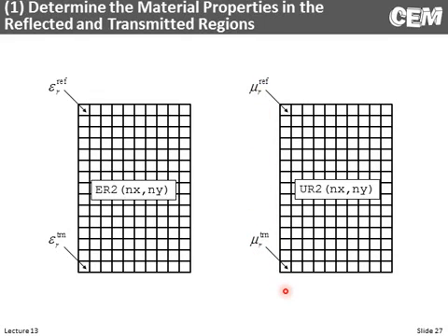Remember, the way we're formulating this with a plane wave source and the way we're calculating transmitted and reflected power requires that the reflection and transmission regions are homogeneous. So our device cannot be here. We need to have all the same values in the horizontal direction. We can have all kinds of craziness in the middle, but at the edges, where we're calculating transmission and reflection and injecting the source, must be homogeneous. Now that isn't an absolute requirement, but we would have to do our sources and power calculations differently.